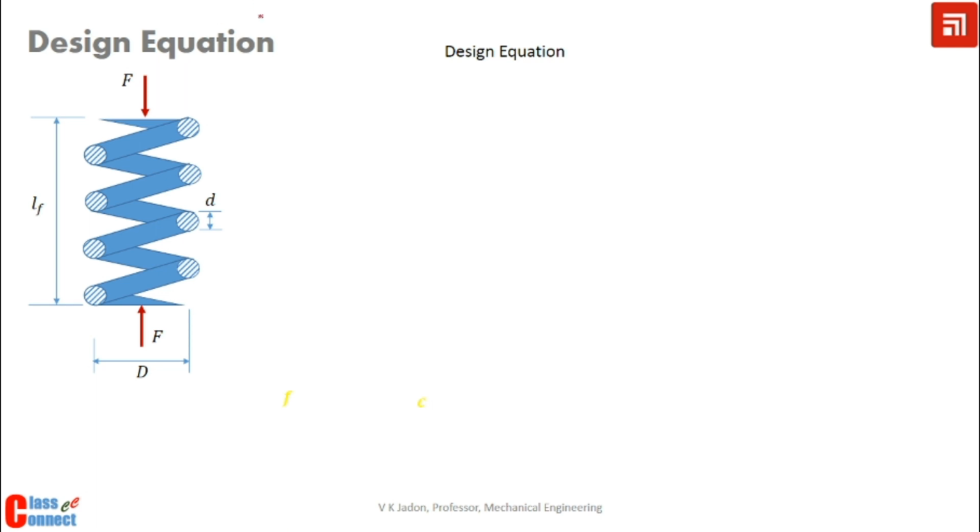The design equation is sigma maximum is equal to sigma D. Depending on which type of load is there and what is the effect of the load, we decide whether it is maximum normal stress or shear stress. As in session 1 of module 2, we have to identify the effect of the load so that we can correctly know what type of stress will be induced in the member.